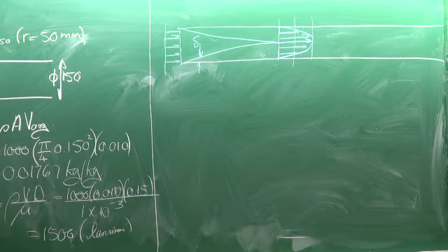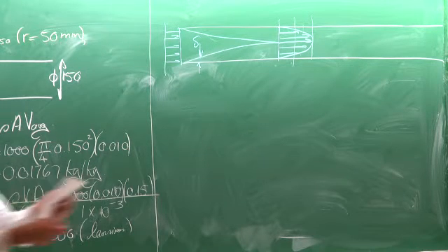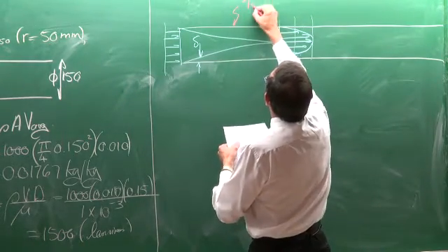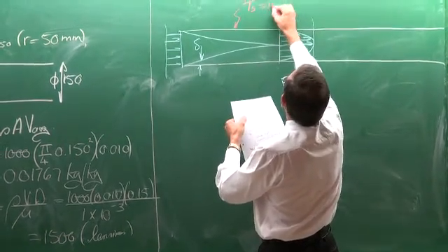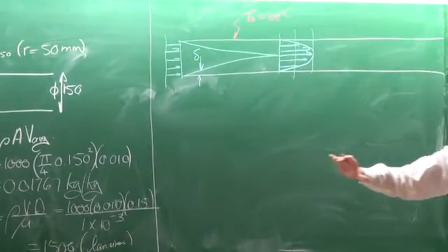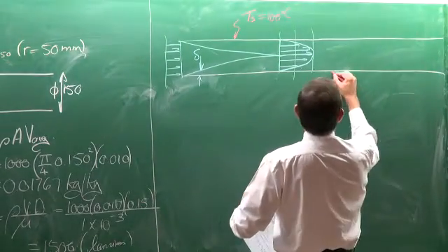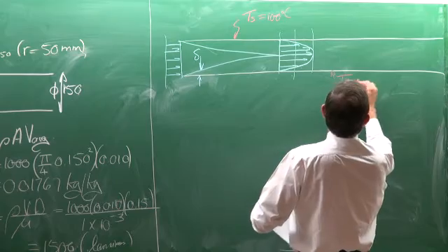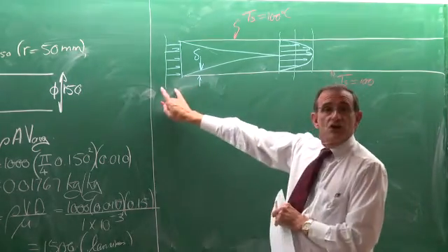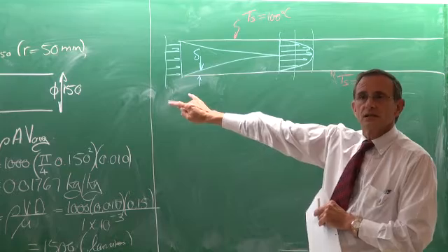Right. Now, on this same problem, what I'm going to do now is, let's heat the wall. So the surface of the pipe or tube all over is now equal to 100 degrees Celsius. So it's a constant, Ts. Surface is 100. And now the inlet temperature is going to be 20 degrees Celsius.